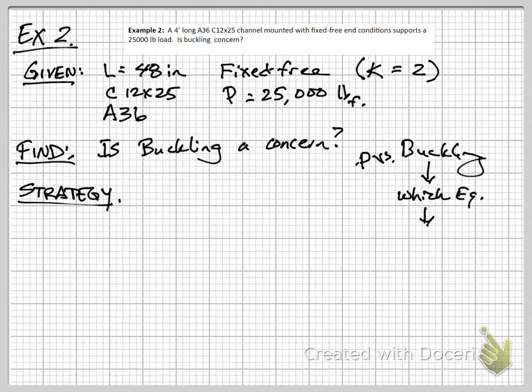And to know which equation, we need to know the slenderness ratio and we need to calculate the column constant. So that's our strategy. Number 1, calculate the column constant and the slenderness ratio.